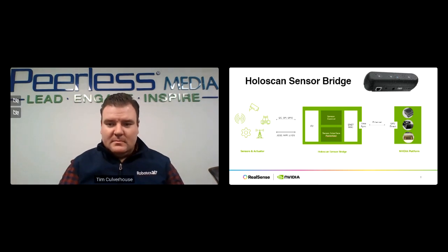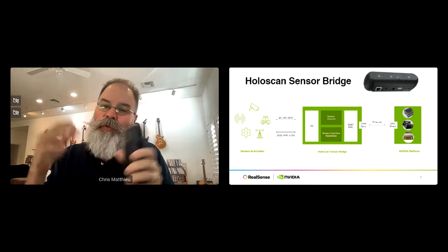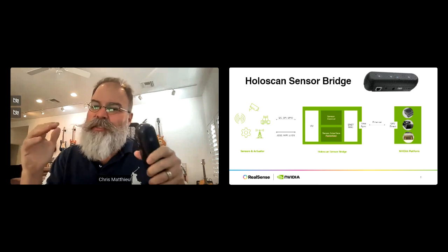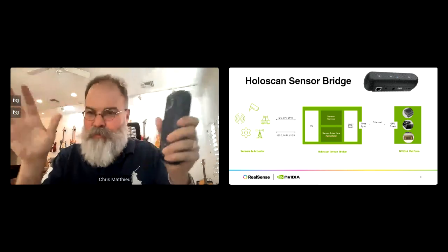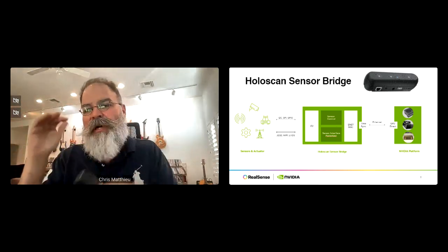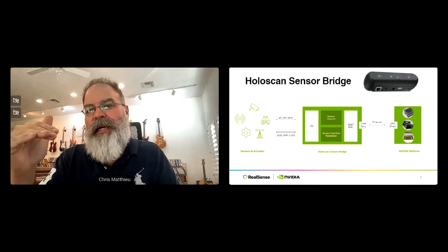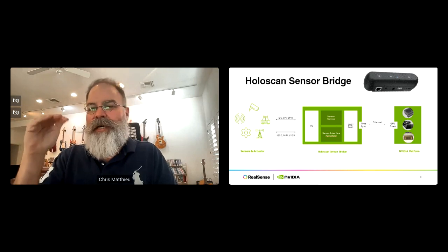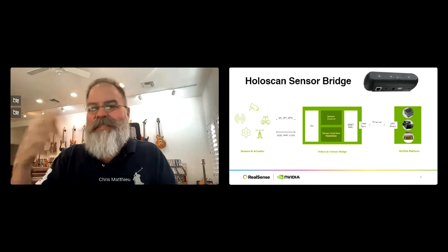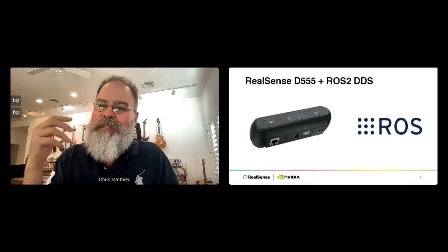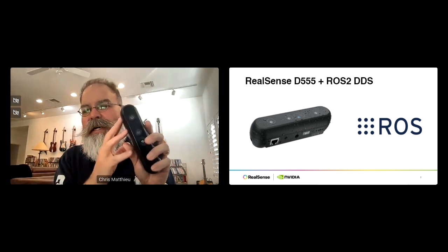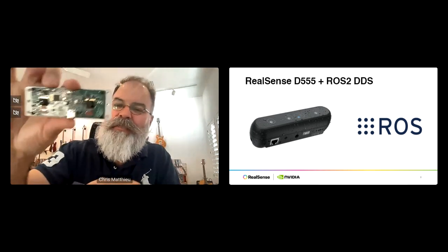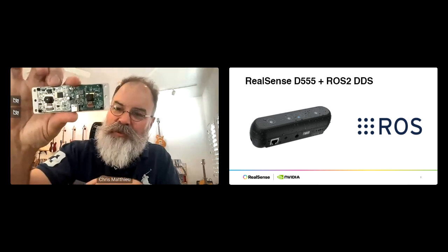Wow, that's a great question. With the traditional RealSense cameras, you have to plug them into a machine that's running, provided you're in a ROS environment, the RealSense SDK, and then you have to install LibRealSense ROS or RealSense ROS. Those are basically drivers that convert the camera's data, just any RealSense camera data, into ROS topics of the stream.